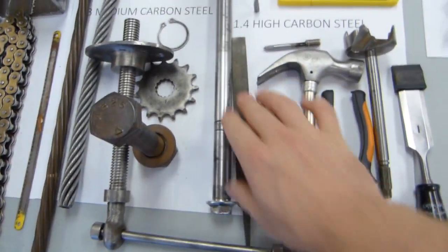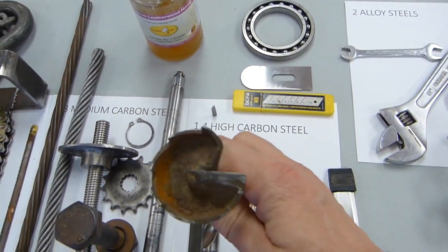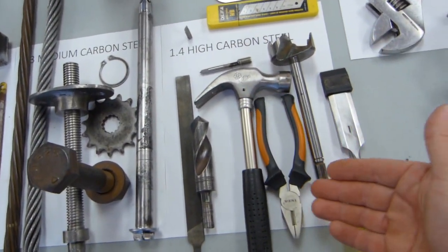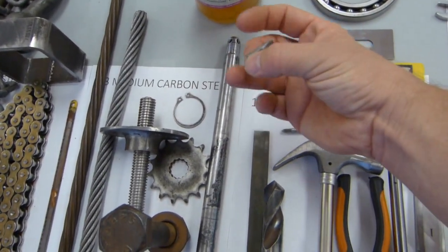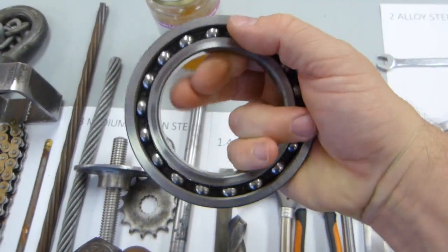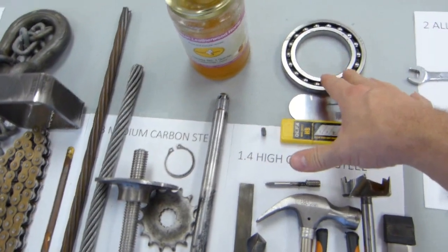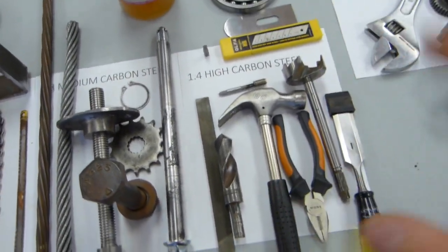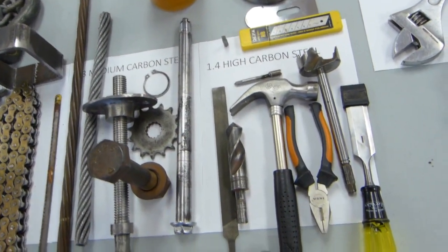High carbon steels are files, some drill bits, especially the drill bits that can be sharpened by those files along their cutting edges. So these kind of drill bits, hammers and pliers and chisels and razor blades and X-Acto blades, some plain blades, screwdriver tips, and of course we've got here a very noisy bearing from an elevator. So bearing balls, outer race and the inner race are high carbon steels. Now of course quality bearings can also be made out of alloy steels, or same for chisels and everything, but the cheap ones and the simple ones, or most of them, can be made out of high carbon steel.